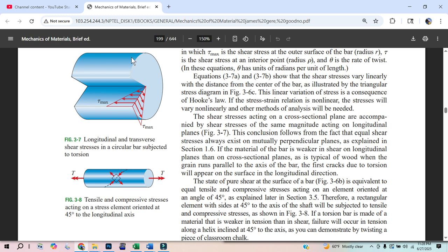shear for rigid materials, those molecules don't travel very far. The angle is really small, 0.004, and the distance between molecules is incredibly small. So that remains a 45-degree angle. Even though you get a distorted shape, you get a break on that 45. Hell yeah, and that's where you get this 45 propagating all the way around a piece of chalk.